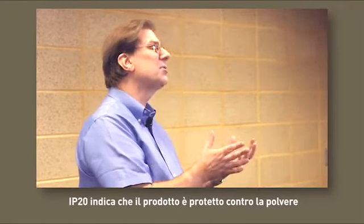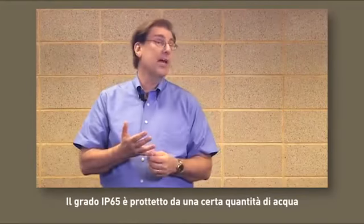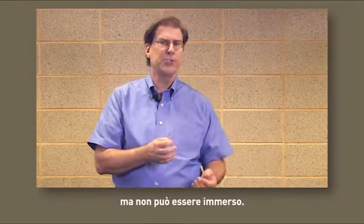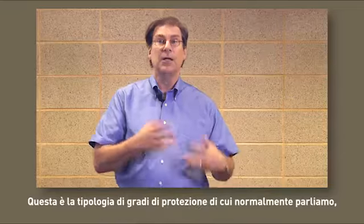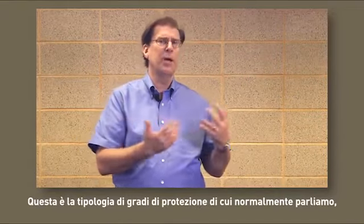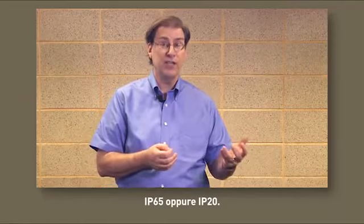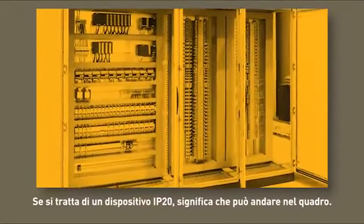IP20 means it's dust protected. It can handle dust, but it can't handle water. If it's an IP65, it can handle a splash of water, but not be submerged. An IP67 would mean I can submerge it up to 3 feet. So those are the kinds of IP ratings that you might hear someone talk about, an IP65 device or an IP20 device. If they say IP20, it's going inside of a cabinet, such as this.